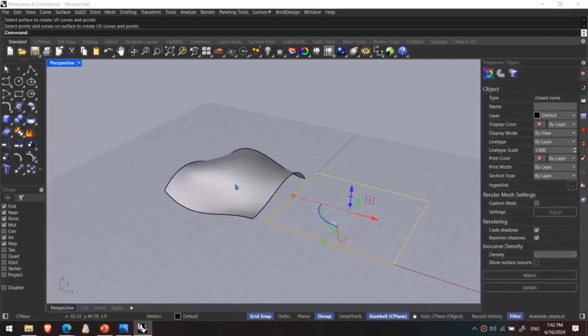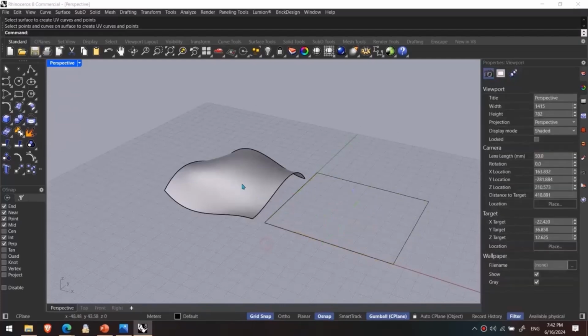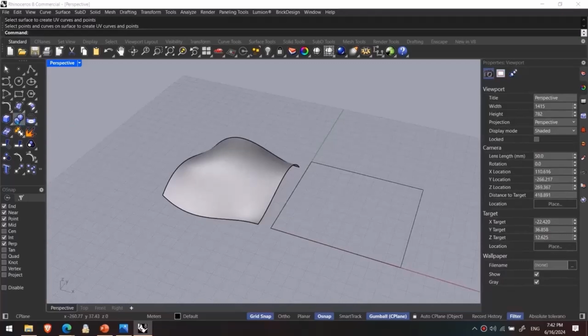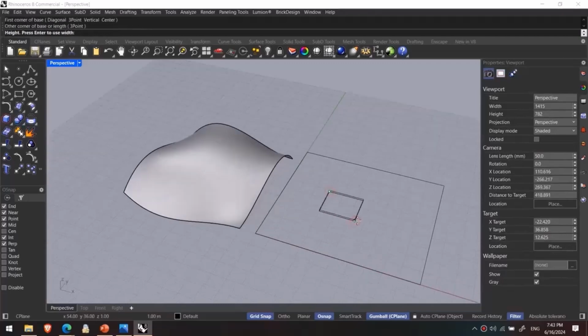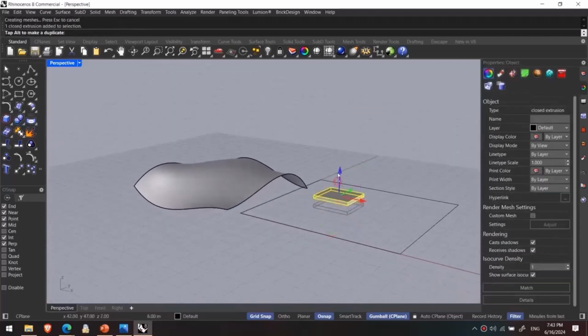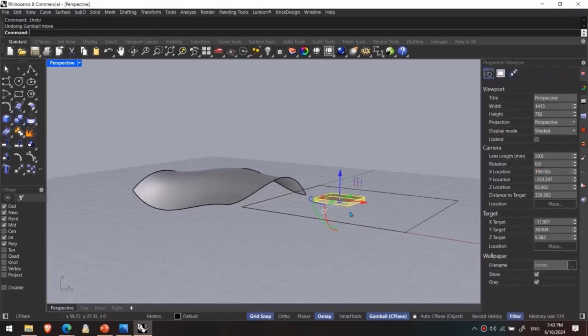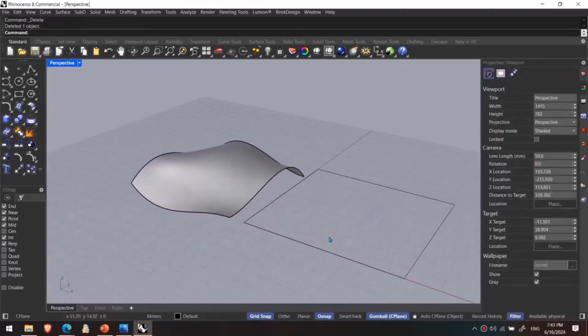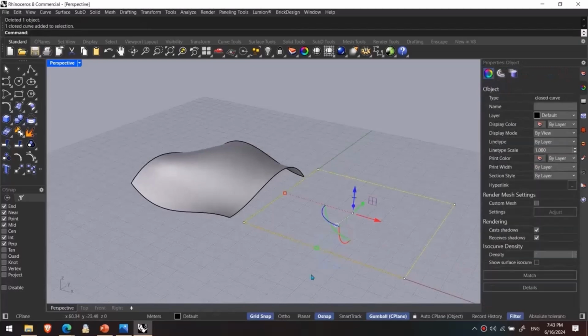But the difference between this and previously, when we drew some patterns on the enclosed region, is that if we here create a 3D box, we should specify its position. So here we cannot consider the lines or 2D patterns as the reference.